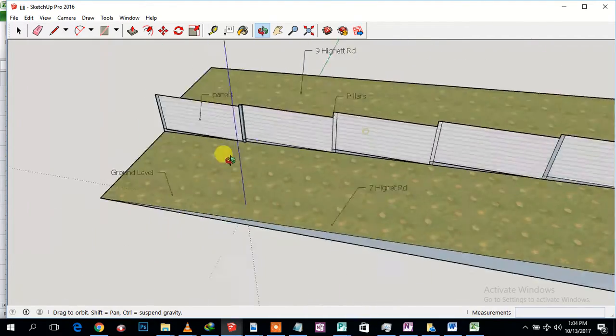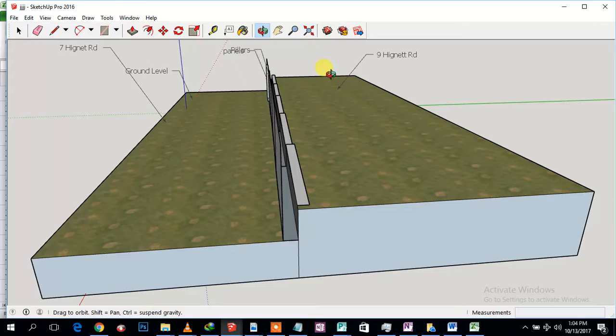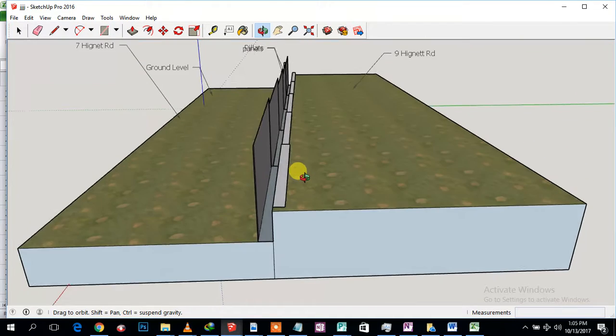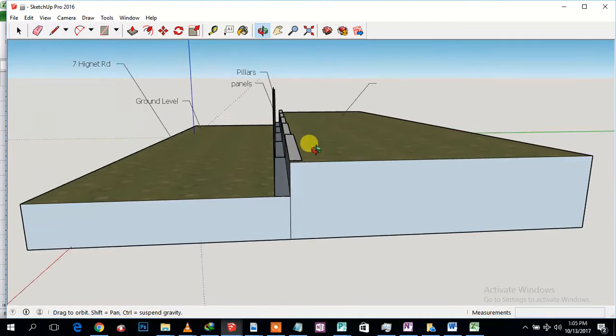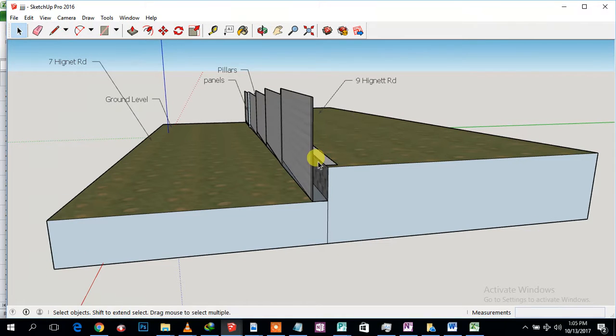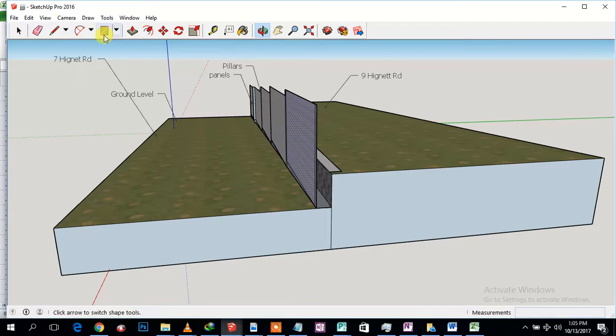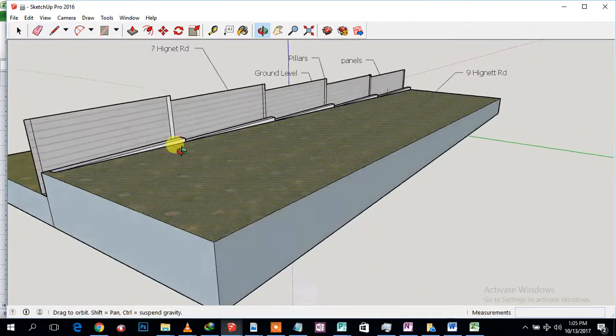All right. Let me just finish up, because I'm going to go to another drawing that I've just done, and I need to explain a few things. So basically, this is what needs to be done. It's a permanent solution. I'm sure you can see that this is the wall that we're going to build up, and it holds this bank, because this is the mismatch. This one is higher and this one is lower, and that's why this wall here, which was built a long time ago, is now falling, because it's holding up the weight of this bank, which is probably a third of its height. Okay, right now that's fixed up. That is as far as the boundary wall is concerned.